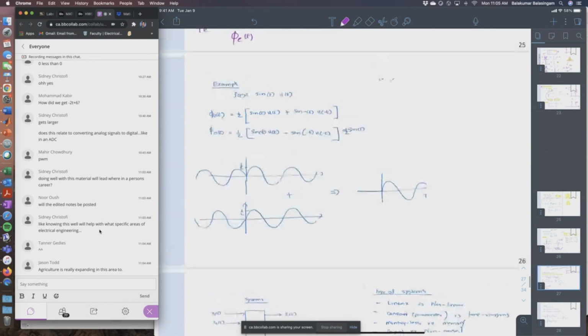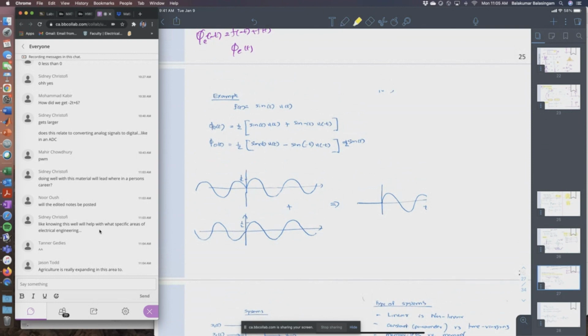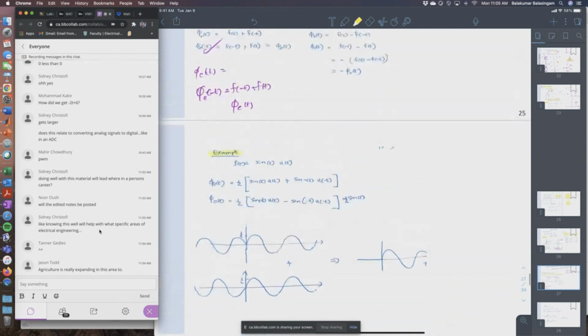So, okay, there's an example here. Example: f(t) = sin(t) u(t). First of all, whenever I see a signal, I want to draw it, and that's always a good way. So let's draw sin(t) times u(t). I'm just sketching it without too much detail, just sufficient detail.